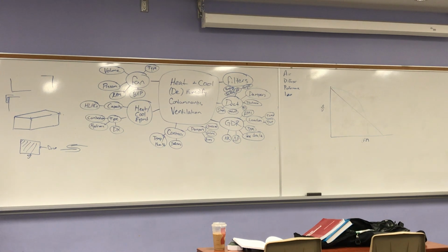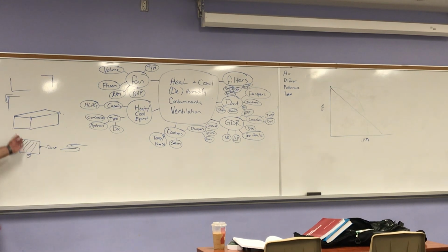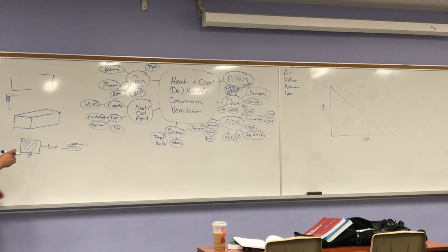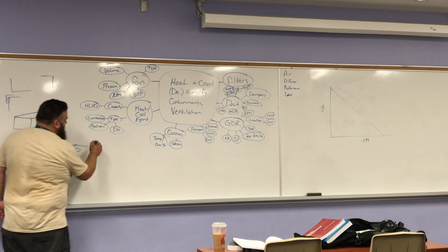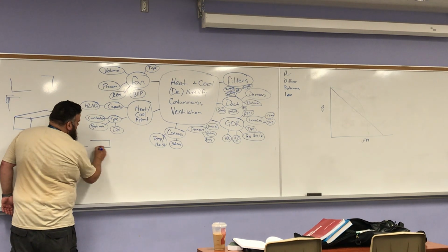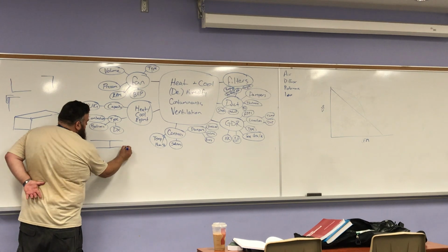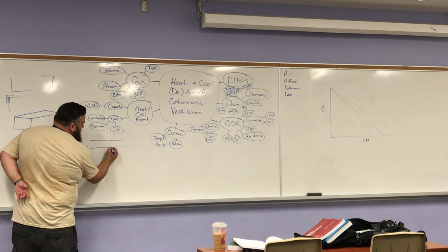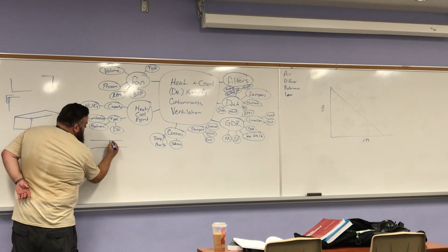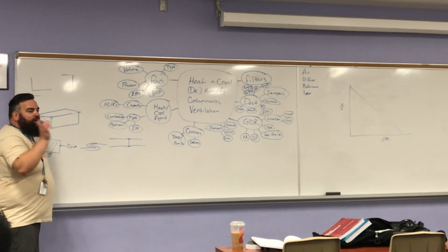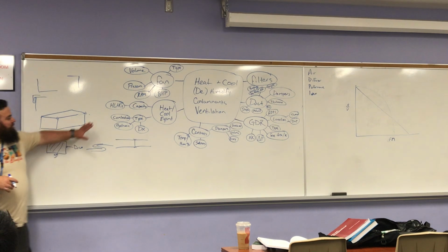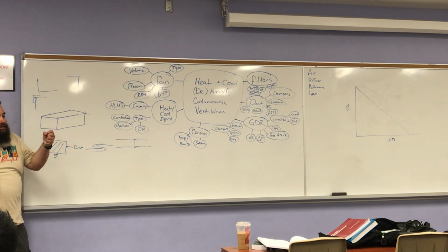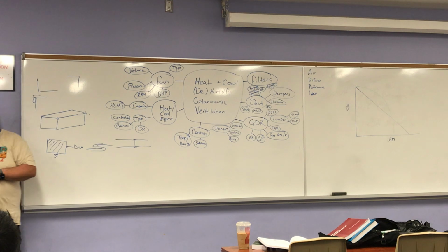Also very leaky. On the drive side here, you bend back a flange. Basically if you had two pieces of duct, I'm looking at the top now, connecting like this, you would have one flange bent back this way, another here, same here. And you would have a C-channel piece of metal called drive that slides over that, pulls the duct together, and you bend it on the top and bottom.